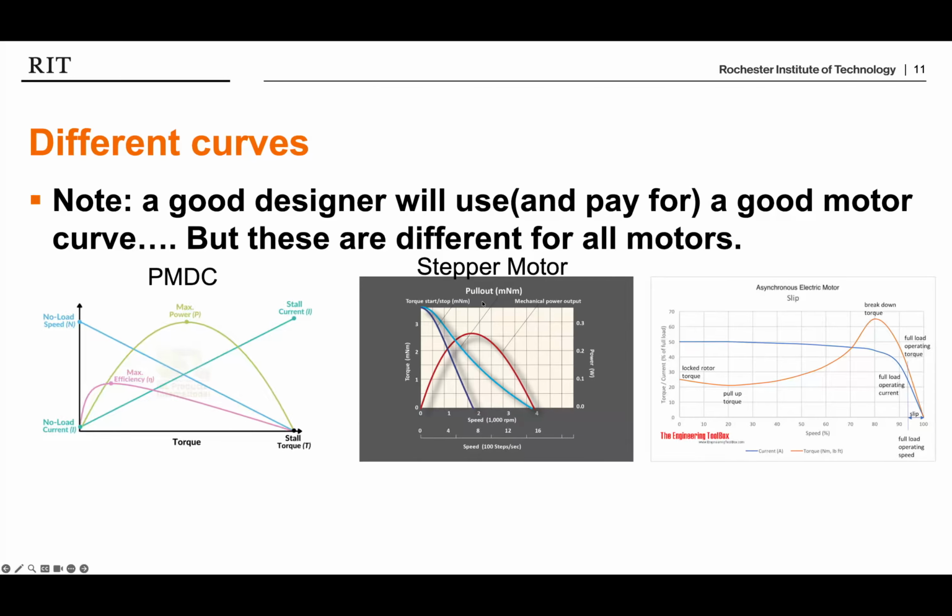All right, last but not least, we have this thing called pull-out torque. And remember that a stepper motor is kind of constantly locking into place, so it's making all of these little locked steps. Well, if you want to change its speed, at any given speed you want that thing to change, it requires a little bit of torque to get that change to occur.